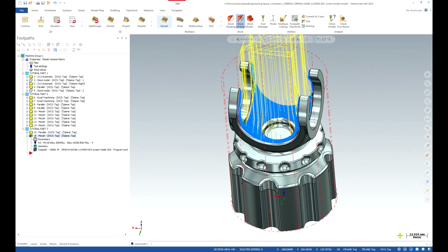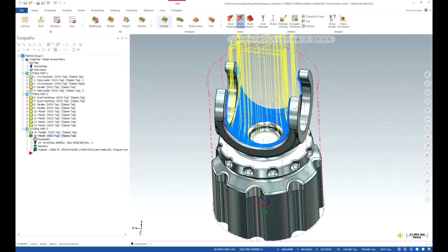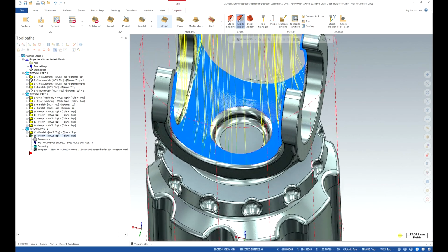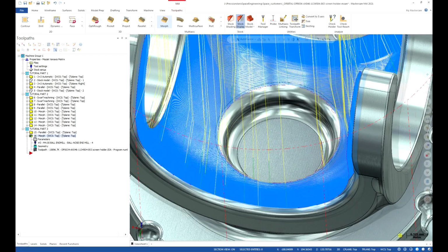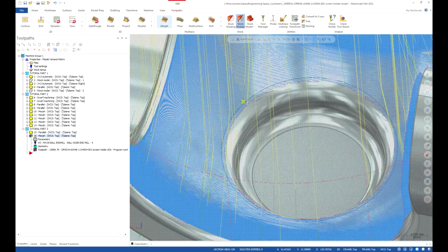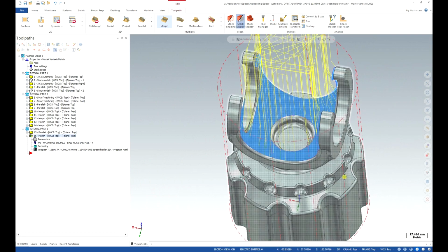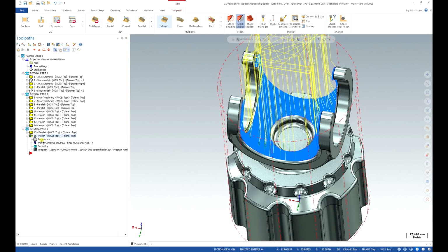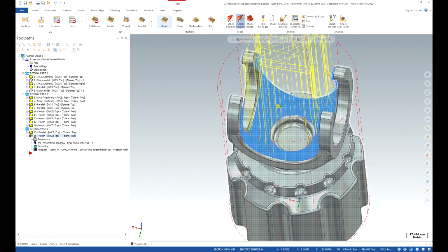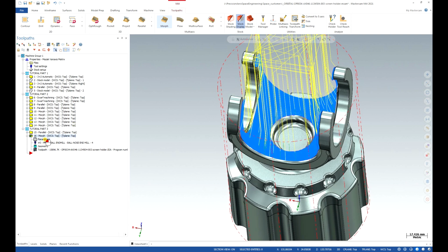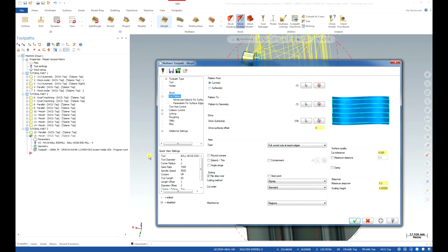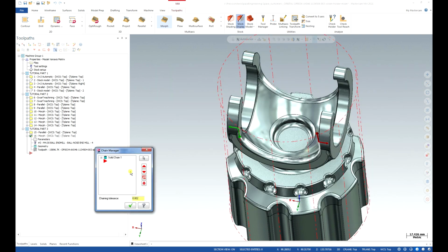Okay, we have our toolpath, but why so many retractions? Something is not right here. Let me have a closer look. Oh yeah, the toolpath is going one way, then the other way. I must have picked something wrong with my surfaces, or actually the curve. I need to double check that, because it should be a nice one-direction zigzag toolpath and then the sides. Let's investigate what went wrong. It's only one pattern here, one pattern here.